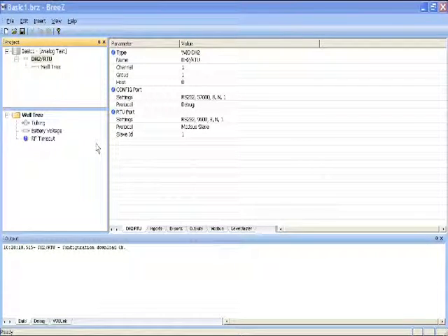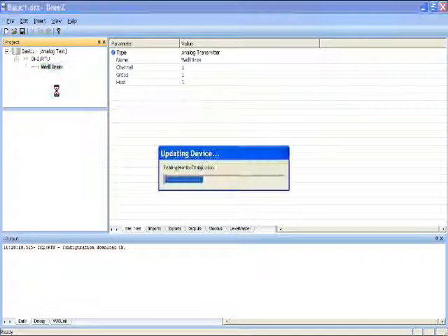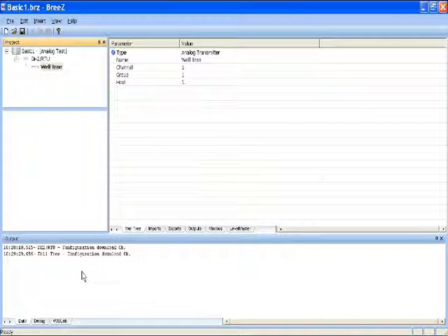Once complete with the updating process of the DH2, then move to update the analog transmitter. Using your pigtail with the 4-pin flat, connect to your configuration cable and connect to the transmitter. Then double-click on the transmitter in the tree, right-click, and click Update Device. In the Build tab, you should see Configuration Download OK. Then you know that each piece of hardware has taken its respective download configuration file and knows its position.